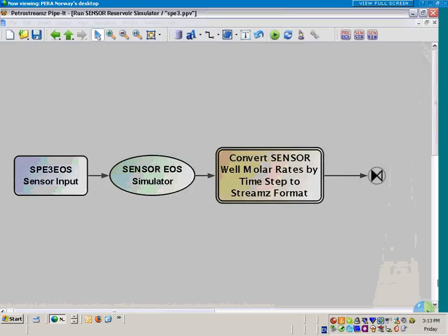So we're looking at a gas condensate reservoir, which in our Excel project we had a dry gas reservoir, so we have more complication. We're going to model the reservoir with a compositional 3-dimensional reservoir simulator. We're going to look at gas injection and how gas injection can improve overall condensate recovery and economic value.